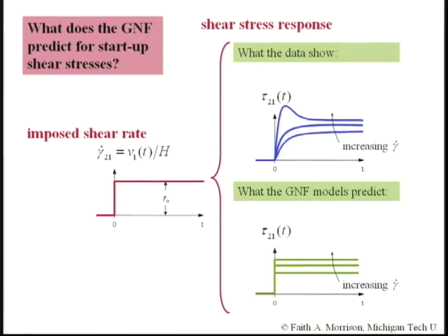Something else it won't predict is to try to get those startup curves better. We worked a little bit on startup curves with my fake constitutive equation. Startup is when you take the shear rate and put it through a step, and we know that the stress comes up slowly and eventually plateaus out. This is pure stress, not eta plus. If it were eta plus, it would go increasing rate this way. This is pure stress. This time-dependent part is not captured by the generalized Newtonian fluids.